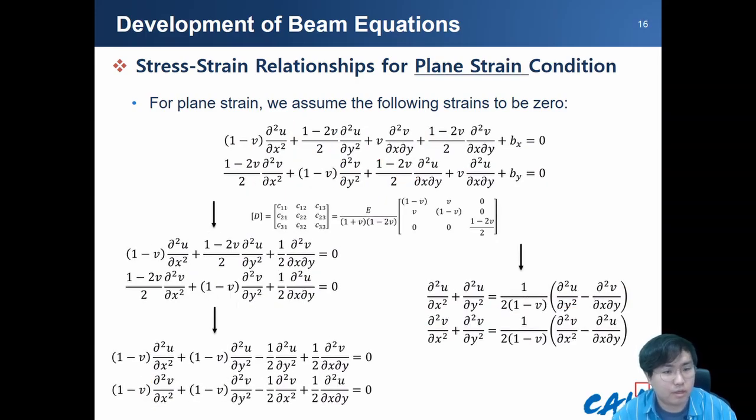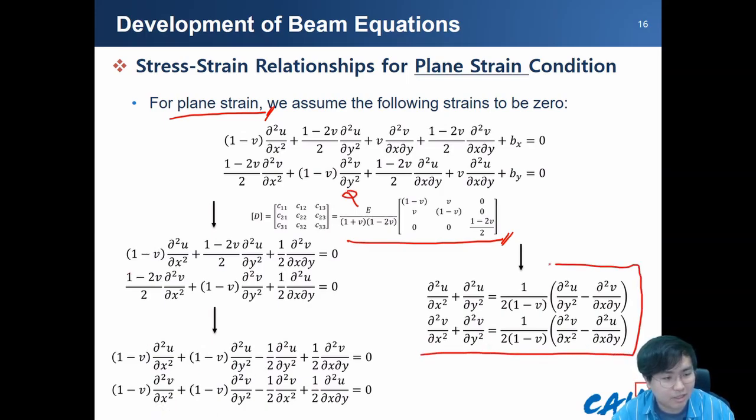Similarly, when you assume plane stress, we have a different elastic stiffness matrix. When you add it here and do some mathematical manipulation, we finally obtain a slightly different partial differential equation depending on your assumption. That is why I prepared those partial differential equations.